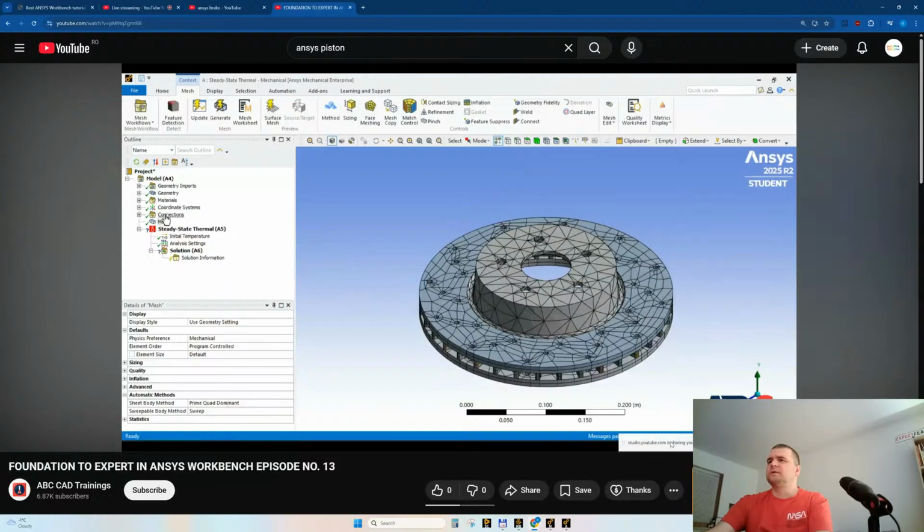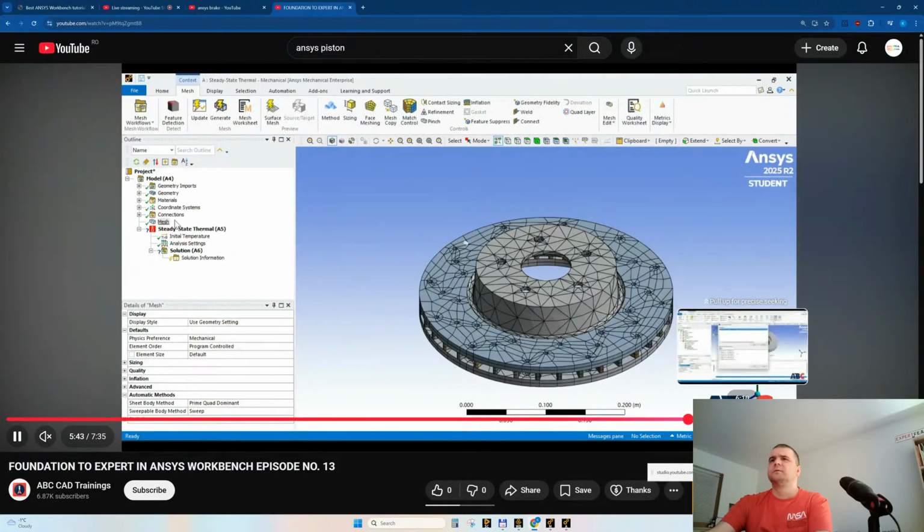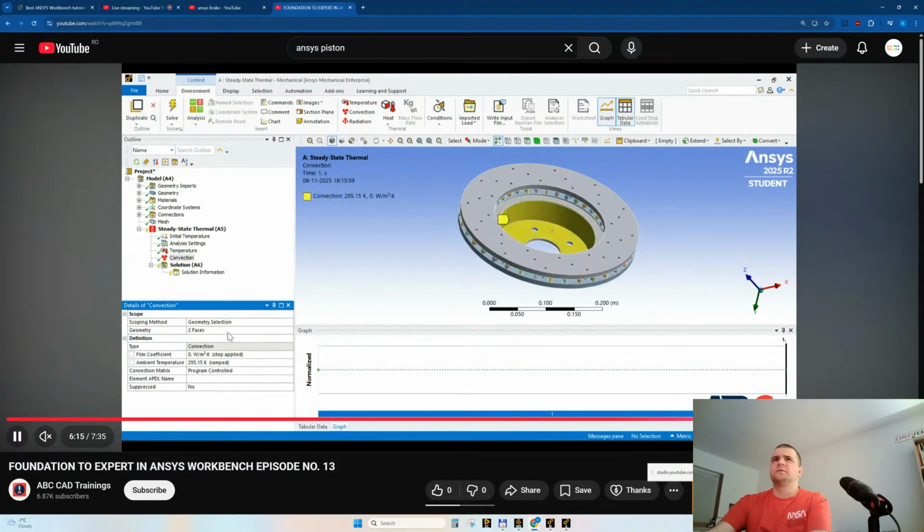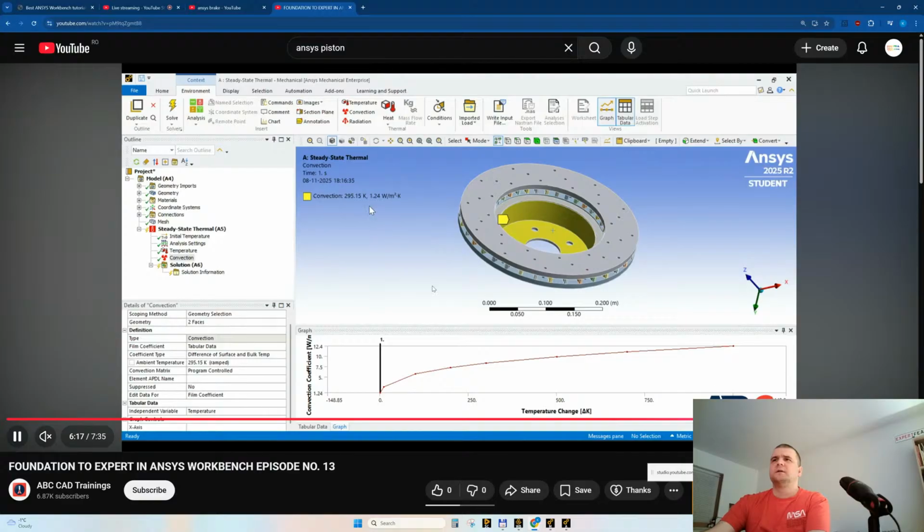It's a thermal simulation. Temperature and convection, yes. Look here, he is keeping separate parts. The ribs are separate parts, which is absolutely not correct, all right? They should be one body. All this should be one body.